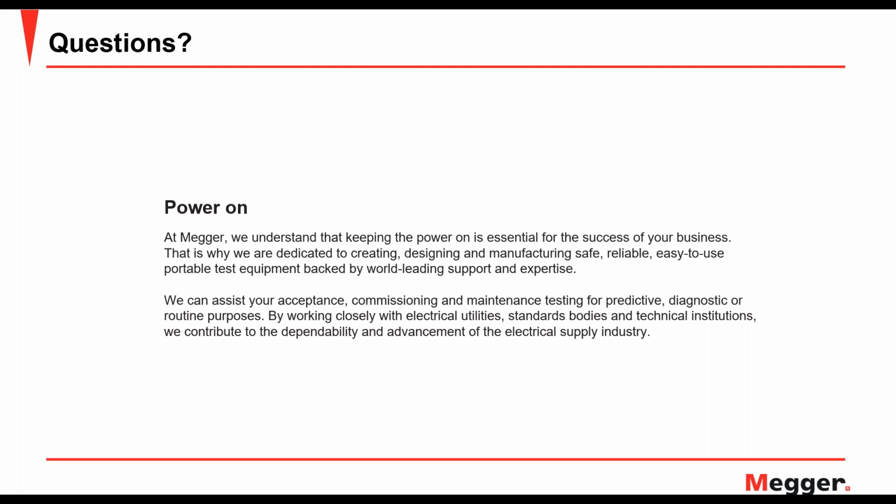Everything else is different. I did mention how you can get the capacitance value from the interwinding capacitive measurement, but that's all you can get. You can get the capacitance value because you get the impedance value of the system. You cannot get a power factor value from a FRAX because the FRAX doesn't do loss measurement.